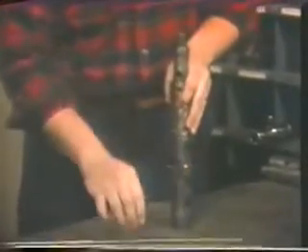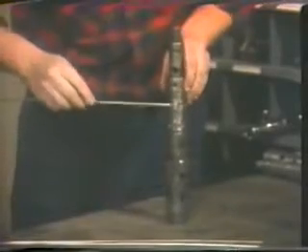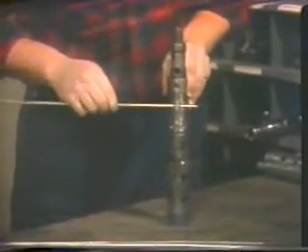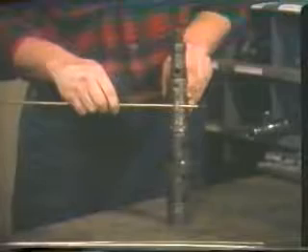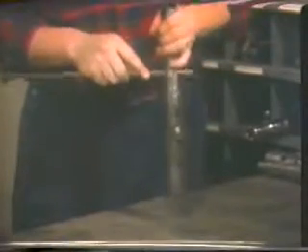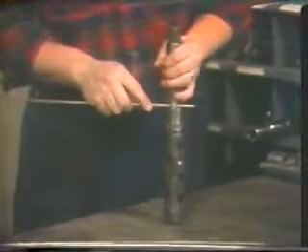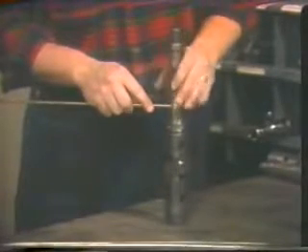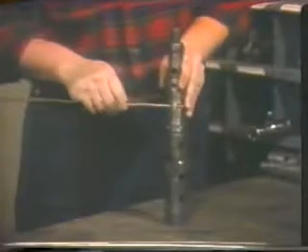In general, these tools are attached to the flow controls by means of shear pins, collets, retaining dogs, or some combination of the three. When the desired depth is reached with the control attached to the running tool, manipulation of the wireline tools places the control in the set or locked position and releases the running tool from the control.